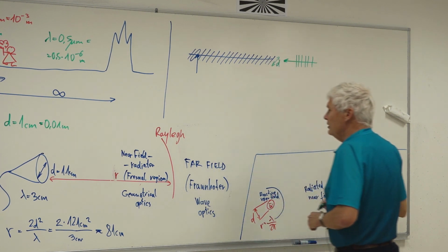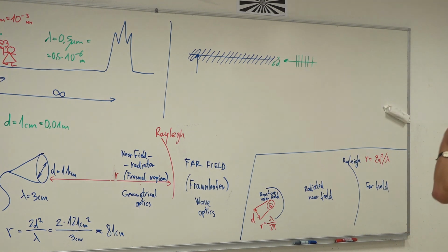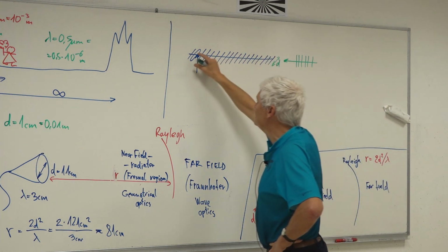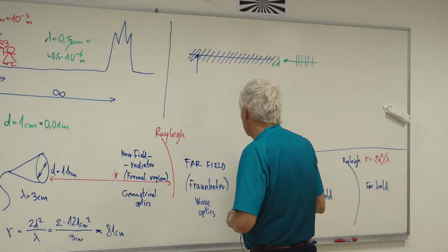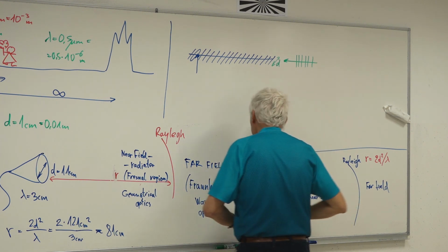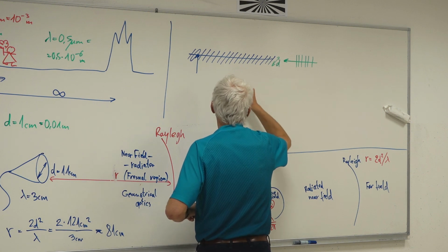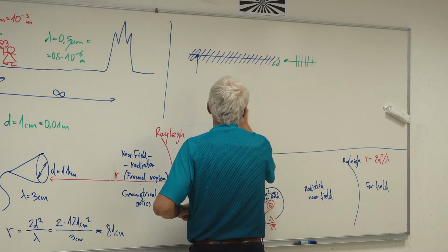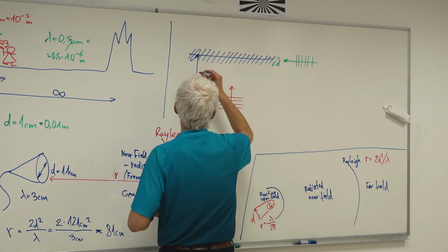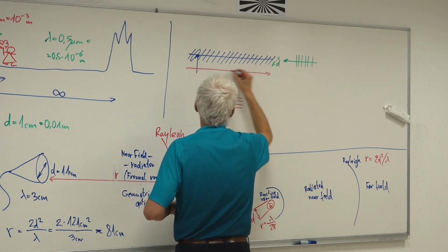So if I observe the main beam of this antenna, it's sufficient to have this short D, the cross section in the transversal direction. But if I look at the side beams of this antenna, so if radiation is coming from the side, then I have to use D, the whole length of the antenna.